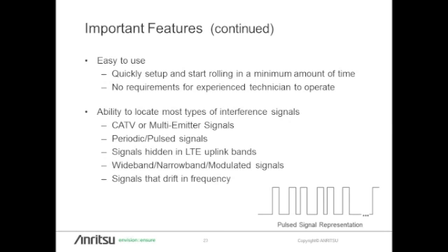And then also very, very important is being able to have a channel bandwidth power measurement. So for signals that drift in frequency, and there are a lot of those signals out there, you need a channel power measurement in order to follow that signal.